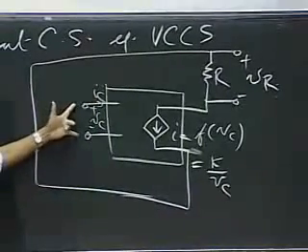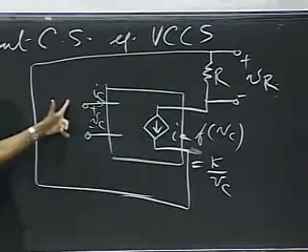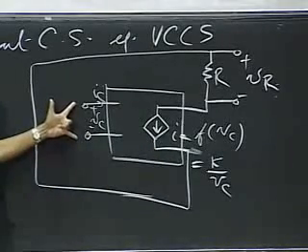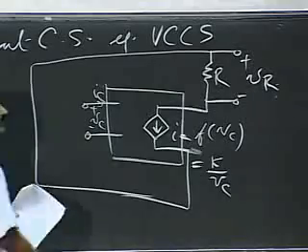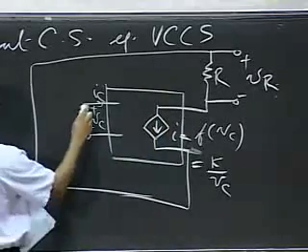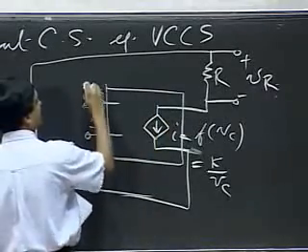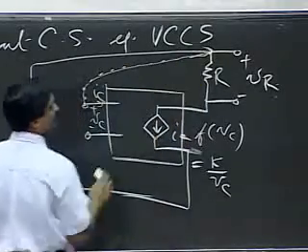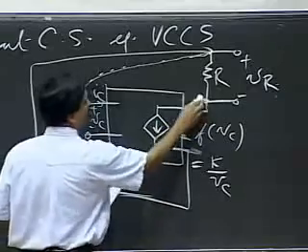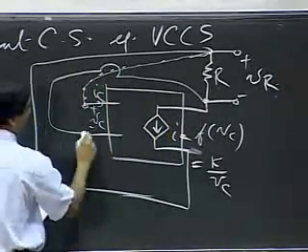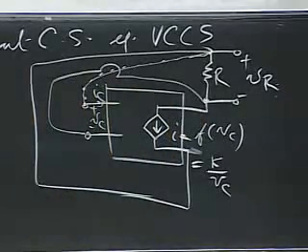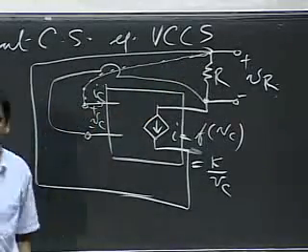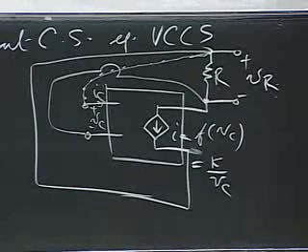So notice that I have to supply some voltage at the input so that the output can depend on the input, because right now, I don't know what the input is here. So what I'll do is apply VR over here. Okay, so let me make this connection from here to here. What I've done is I've applied VR at the control port of the dependent current source.